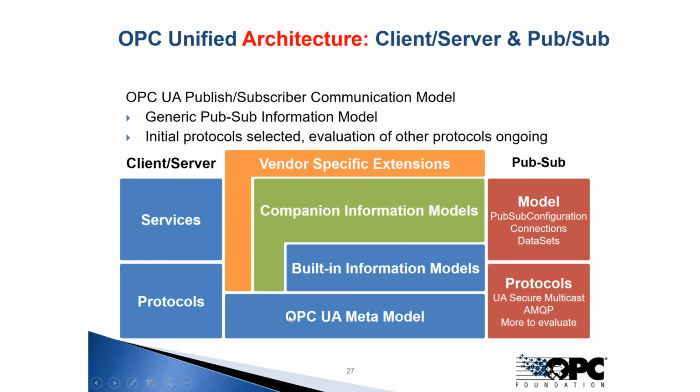And this is exactly what's happening right now with the so-called PubSub implementation. While on the left side, the client-server architecture is really a confirmed communication based on TCP, a one-to-one relationship, PubSub is an unconfirmed communication, which is super fast in a broadcast way.